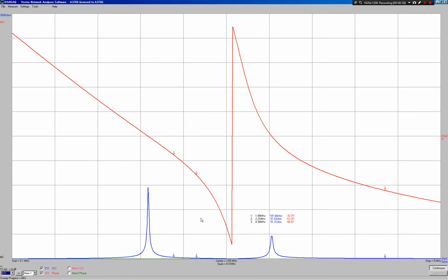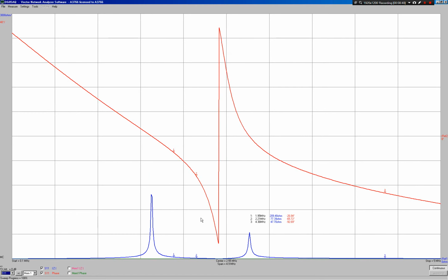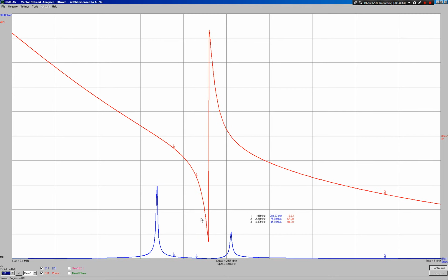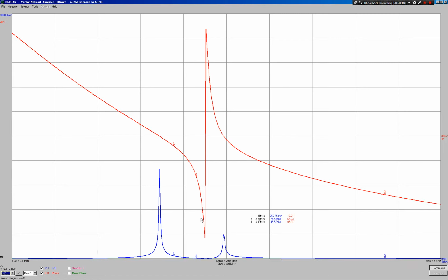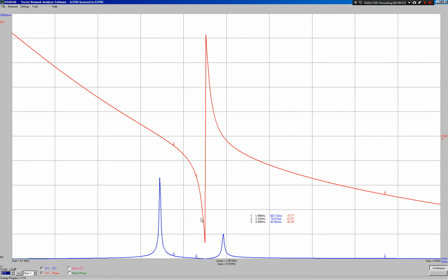Okay, so what I'm going to do, we're actually over-tuned here. We're over-coupled and we've got too much loading capacitance on here. So we're going to balance this up now. I'm going to increase the spacing between the two and bring it back to an optimum point, a coupling coefficient of around 0.2, and I know for that system that means the spacing between the coils withdrawn by about 5 millimeters. I'm going to come out a little bit further. That's around about there.